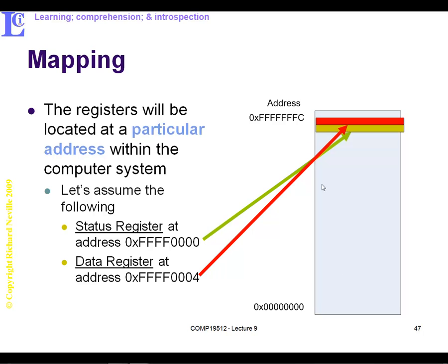So now you can see that memory mapping is breaking down the memory into locations where different parts of information are stored, like the primary memory, or different I/O through the registers is accessed. The processor only has an address bus, but the address bus can get to and read and write data to and from RAM, or I/O devices which can transfer data into this memory addressable location via two different types of registers.